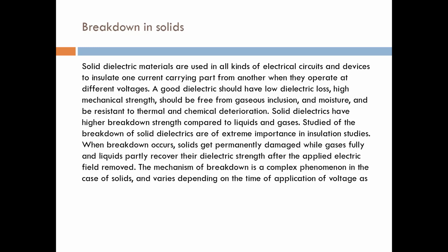Always remember, we have studied breakdown in gases, breakdown in liquids, and now we are studying breakdown in solids. One difference between these three is that in gases, once the dielectric strength is lost, it can be regained if the electric field is removed. In liquids, it is not fully recovered, but partly recovered.